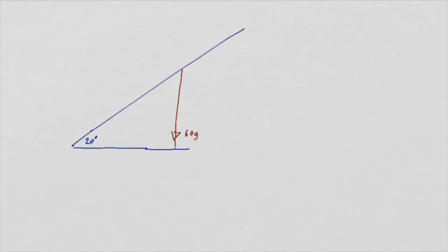One of the tricky bits in this question is the resolving of the 60g force into two components. So I'm just going to have a little look at that. We'll start off with a basic diagram. We'll also extend the force down to the floor in the situation, and then we'll put a perpendicular to the slope from that point.